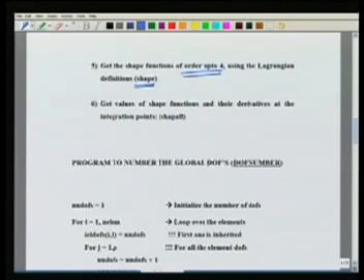Okay. So this routine shape would output that. Then we had decided to have another routine which will take these integration points that we have obtained out of integ points, and at these integration points it is going to output the value of the shape functions and their derivatives in the master element and store them away. This was done in the routine called shape-all.